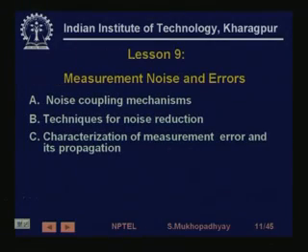Then phase sensitive demodulators. In many cases the raw signal out of the sensor comes in a modulated fashion, for example LVDTs or strain gauge bridges. So, one needs to extract or demodulate the actual process variable that one is interested in. That requires a phase sensitive demodulator circuit. So, we introduced that. Then various other kinds of circuits like sample and hold, multipliers and multiplexers we talked about. Then we took a look at measurement noise and errors.